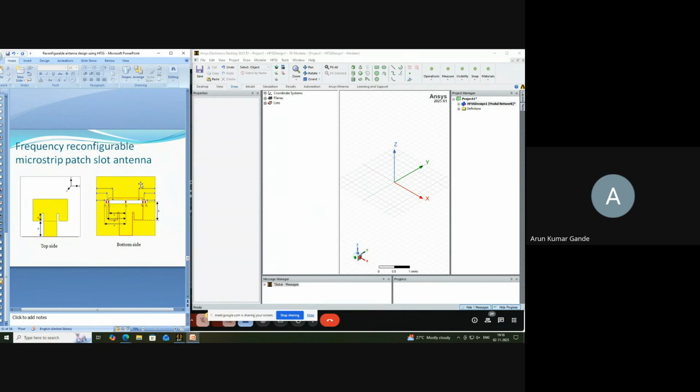So top side we will be applying the positive voltage, bottom side we will be applying the negative voltage or the common potential or ground potential, right? So these horizontal slots that we are having here, they are used for segregating the positive plane of the supply with the negative plane of the supply. And then we are having 2 more slots here on the right side and 2 more slots on the left side. These are used for separating the biases for the 5 diodes, right?